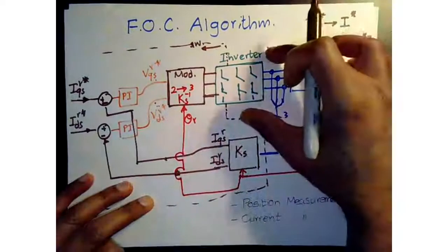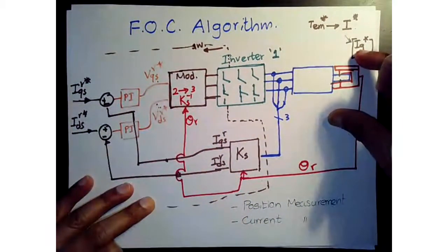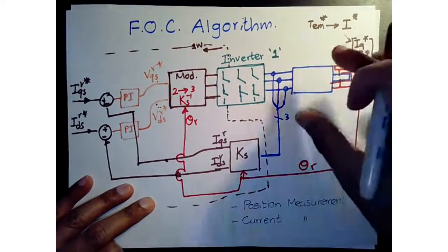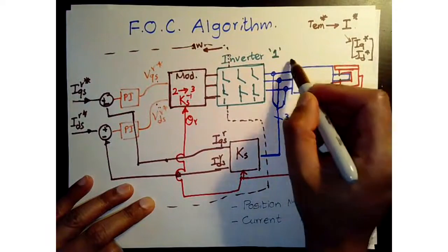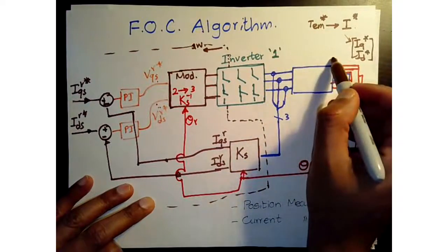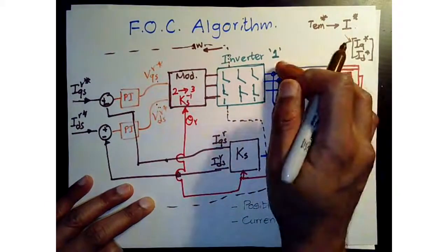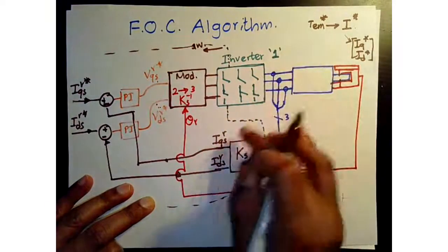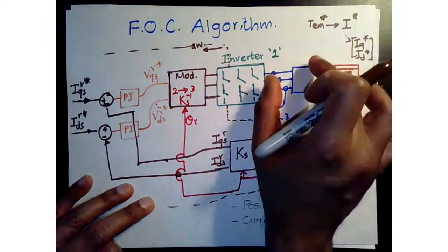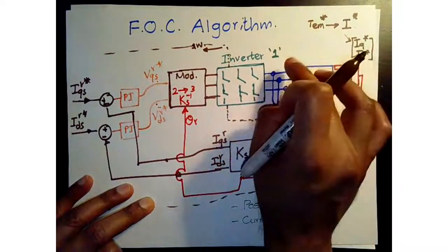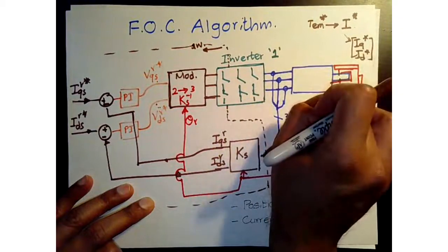So all those concepts will apply because you can even model this motor in the rotor reference frame. We did that, right? So now you can say, I have one equation for the Q axis, one equation for the D axis, and you can even assume for your model that you're measuring ID and IQ directly, and you have the corresponding LQ, LD, and the resistance values for each of those differential equations.